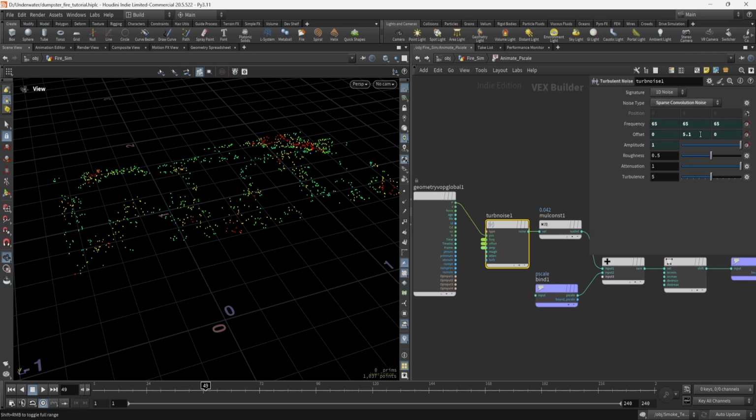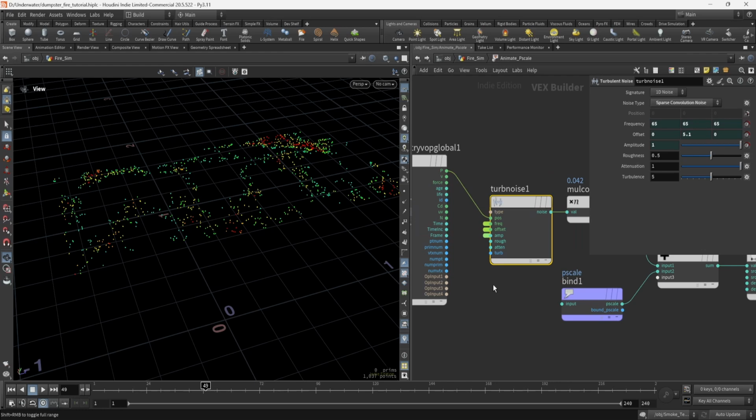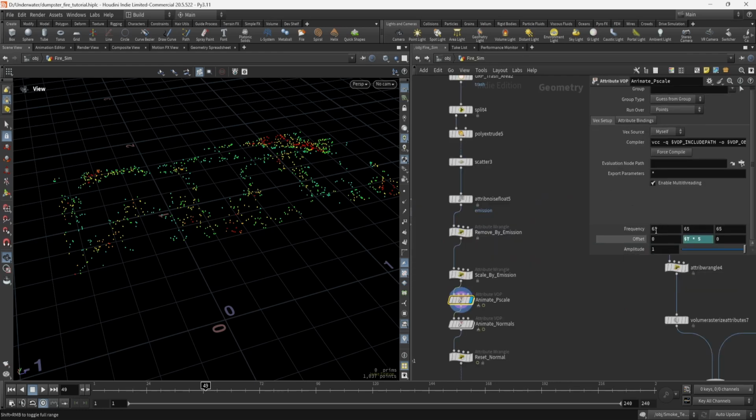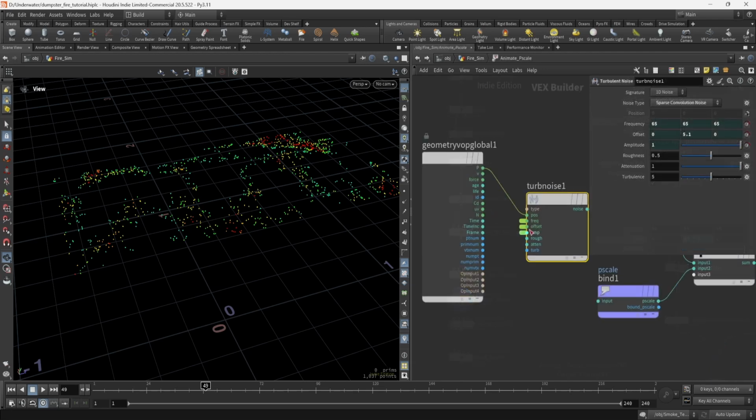And anything in green here is stuff I promoted to a variable so I could access it at the top level. So that's these fields, right? And we need to do that to add time with an expression. And to add any of these as an attribute at the top level, a parameter, you just middle click and do promote parameter there, and that'll do that.